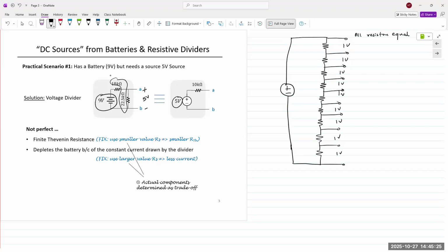Okay. This is in fact what happens inside your laptop adapters. Okay. A laptop requires multiple different voltages inside itself. One to power the CPU, another one for the graphics card, another voltage for the memory sticks. They all could be the same. They could all be different. USB ports are 5 volts. Digital logic circuits are typically 3.3 volts. So there's 2 voltage combinations right there.